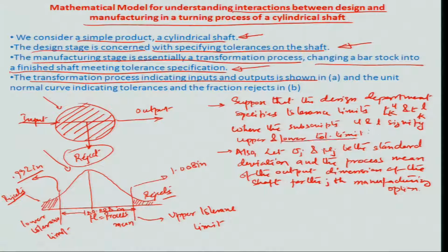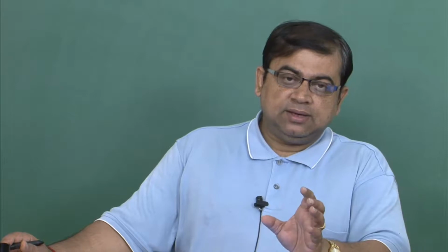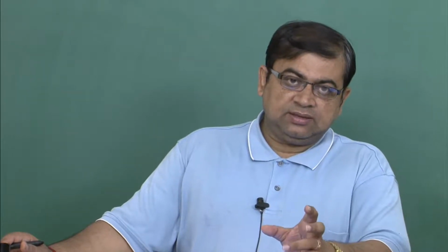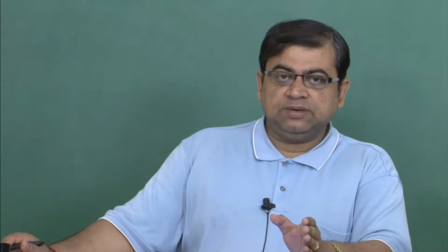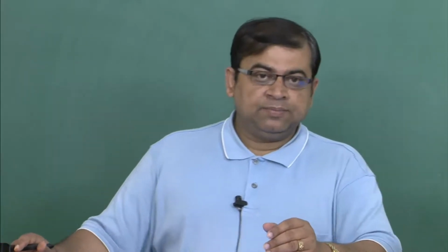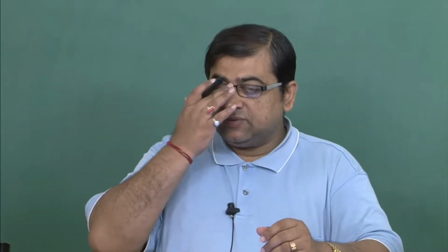So this tolerance limit is as per the kth system of tolerances. And there may be many such systems of tolerances which may need to be incorporated while doing the designing, and so therefore there has to be a generic approach saying that a particular tolerance of the kth type is being matched according to the machine capability, where there is a jth manufacturing option being evolved for the kth particular tolerance on the design of a certain part.